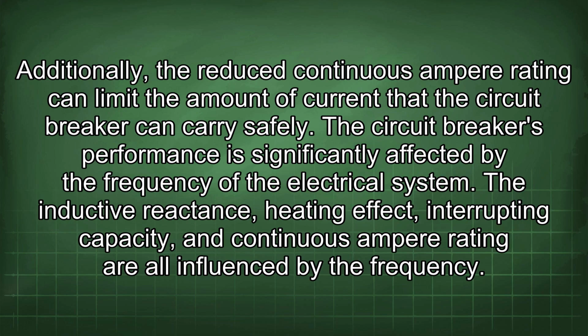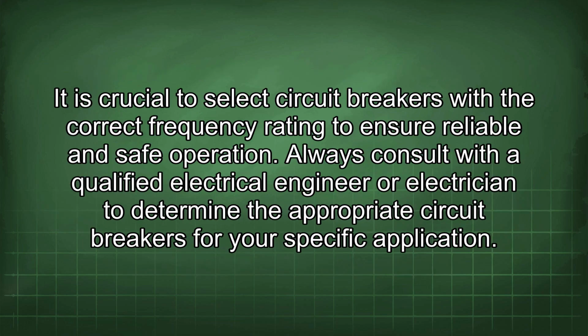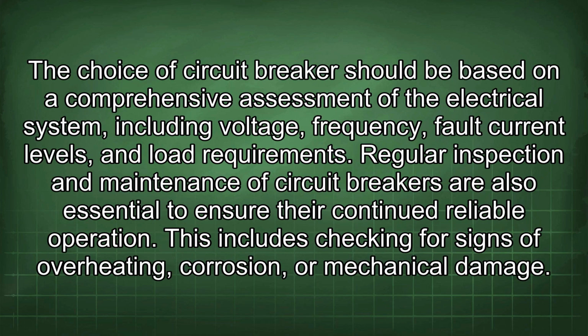The inductive reactance, heating effect, interrupting capacity, and continuous ampere rating are all influenced by the frequency. It is crucial to select circuit breakers with the correct frequency rating to ensure reliable and safe operation. Always consult with a qualified electrical engineer or electrician to determine the appropriate circuit breakers for your specific application. The choice of circuit breaker should be based on a comprehensive assessment of the electrical system, including voltage, frequency, fault current levels, and load requirements.